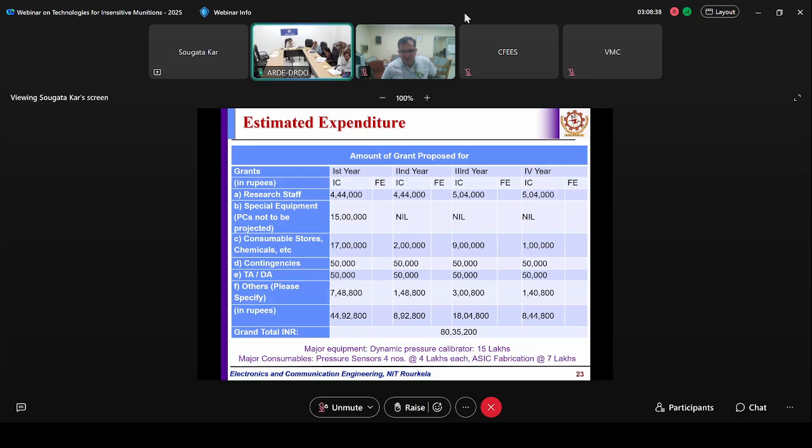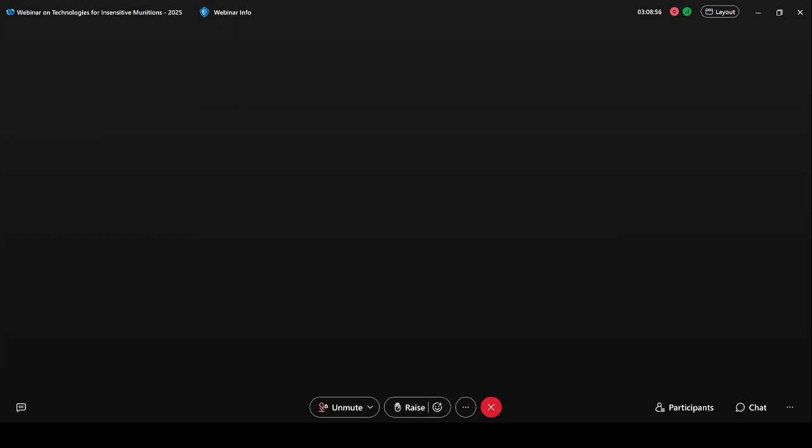So what is so special in there? What is the difference between these two systems? Sir, actually your voice is breaking, sir. Sir, the difference is the requirement: the pressure profile changes very fast, and the most measurement, the acquisition time, is within maybe 80 milliseconds. Here we are interested in only 10 to 20 milliseconds. That is the only thing, that we need a fast system. But I find that that sensor is only a charge-based sensor, but mostly we are using voltage mode sensors. IEPE standard sensors are there.